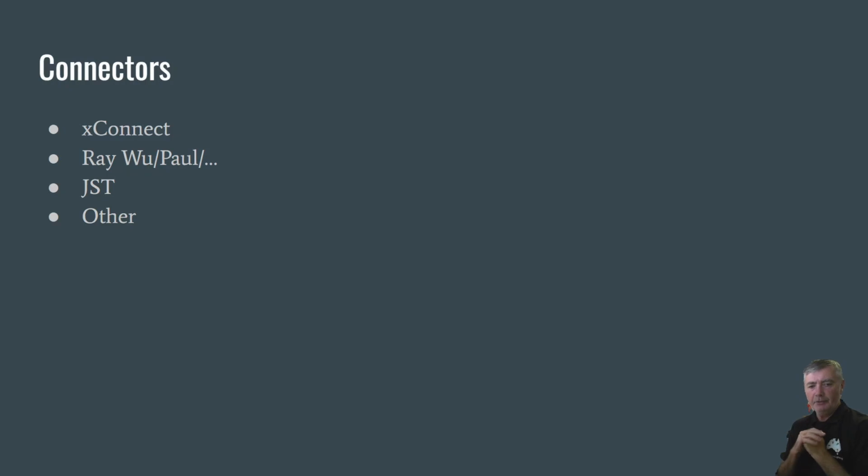If you're buying the lights cheap on Alibaba or Amazon, they'll often come with a JST connector, which is this flimsy little 3-wire connector. It's not a great connector, but at a push it will also work. I have a number of them that I run outdoors and have run outdoors for a number of years, and look, they work just fine as long as you're not unplugging them and plugging them in all the time. They just seem to work, but they're not waterproof, and I definitely wouldn't recommend them as a way to do a quality show.